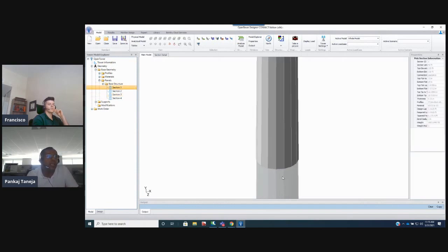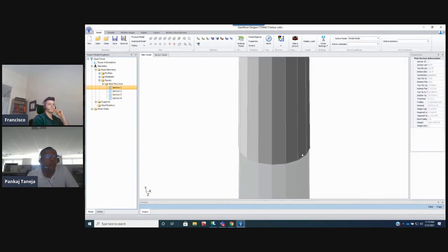Let's look at it this way. You have this outside pole diameter flat to flat, reduce the thickness of it, and that's the inside diameter of the top pole of the bottom section, and multiply by 1.5 is the requirement of the lap splice. Got it. But how do we do the interaction, like, hey, it's a slip joint? Definitely. And when we are pushing this, we combine the section properties of the inside pole and outside pole only at that level.